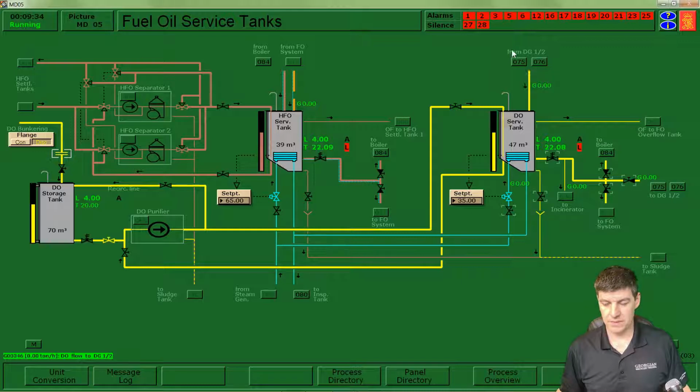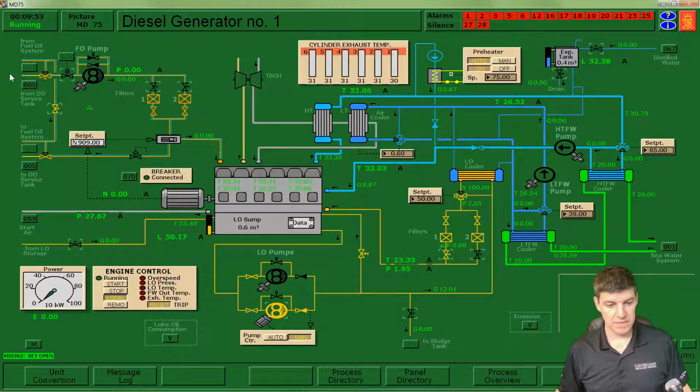Okay, there's a couple of them, so I have a spot 2 diesel generator 1, and I also have a return pathway from diesel generator number 1. So I'm going to supply fuel to my diesel generator number 1. And that brings me here for fuel. And I'm going to continue across. I have a valve to open up and then a bank of filters.